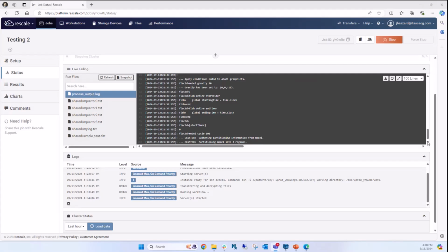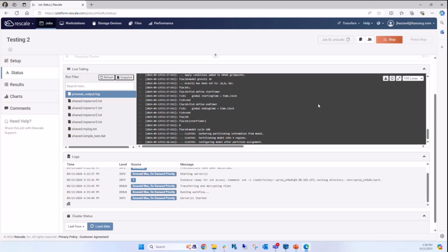So this takes a little bit of time. It's dividing up the 8 million zones into 4 different pieces, configuring the model. And here we go. Process 0 has 24,589 ghost grid points. Process 1, process 2, process 3. So what actually happens is that the grid points at the boundary between the different sections of the model are actually duplicated. So you have these ghost grid points. So this tells you something about the amount of communication required between the different pieces.